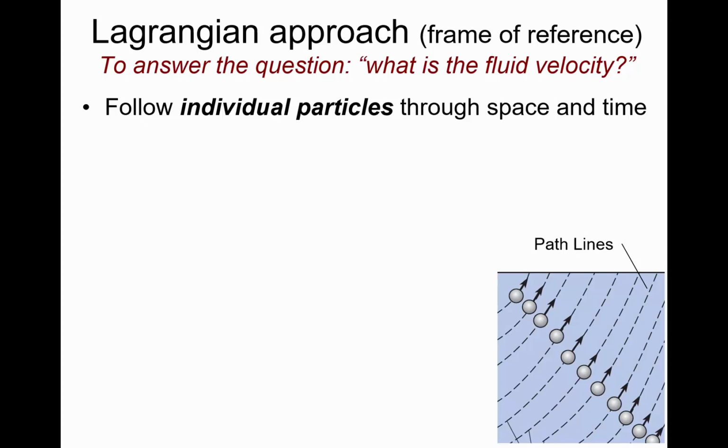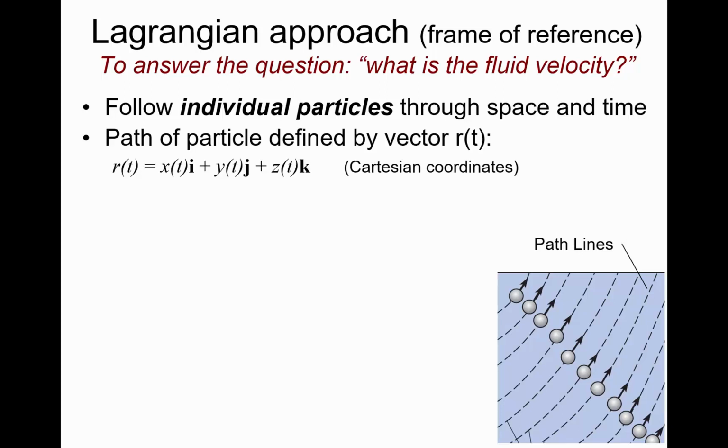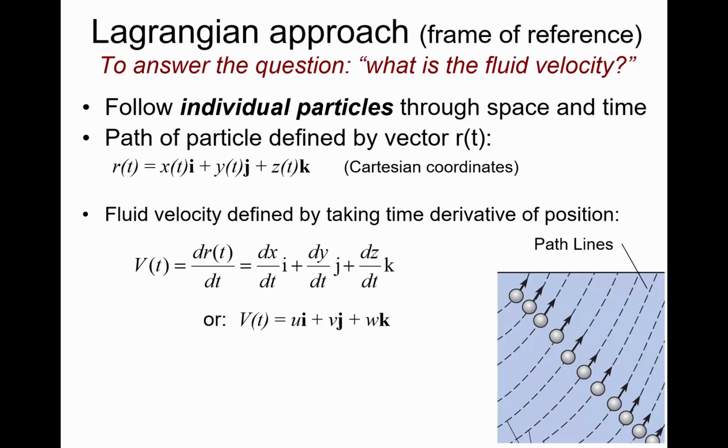And even if it's not every particle in a system, we may want to track the trajectory and the velocity and the characteristic of representative particles, so that if you follow 1,000 particles through a system and you see trends, then you can extrapolate those trends to the fluid more generally. And so in the Lagrangian approach, what we do is we would look at a fluid particle in 3 dimensions, and we would track its velocity in x, y, and z.